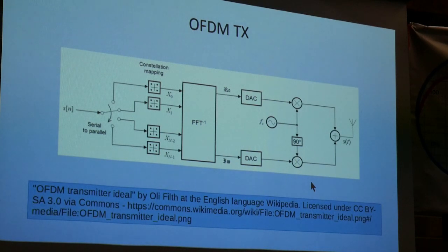As long as you can get a good enough signal to noise after you've been through all that processing, it's good enough. Because you're adding 8K into one bin, so you need a bit of headroom. But you've got all this error correction sitting on top of it: trellis decoding, a Viterbi decoder, Reed-Solomon, all that going on as well. So I don't know is the right answer, but I'm guessing it might not be as much as you might think.